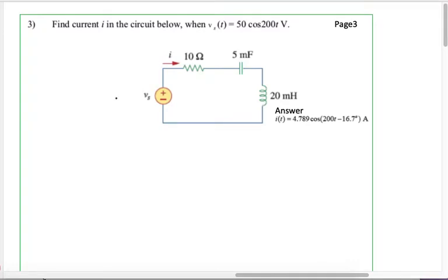In a DC circuit, you can see that the Vs or the supply is one constant value, but here Vs is given as a sinusoidal waveform. So this is an AC signal. So you have to change everything into a frequency domain. Now this circuit is in time domain because we have t here. So we want to change it into frequency domain.